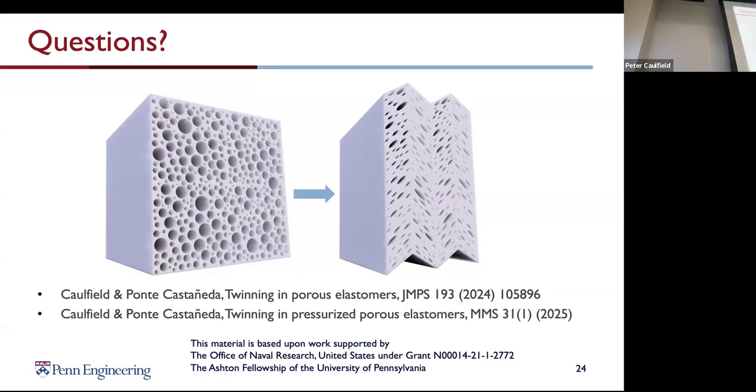Yes. So mathematically, homogenization corresponds to an infinite separation between the length scale of your microstructure and the size of your specimen. And in this case, you would have basically two of those separations of length scale. So the difference between the size of the pores and the size of these layers mathematically should be infinite. And the difference between the size of these layers and the size of your macroscopic specimen mathematically should be infinite.